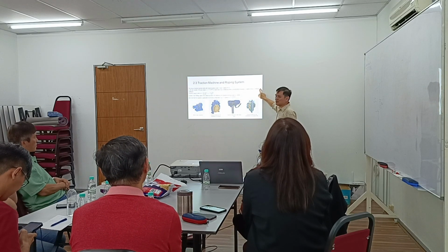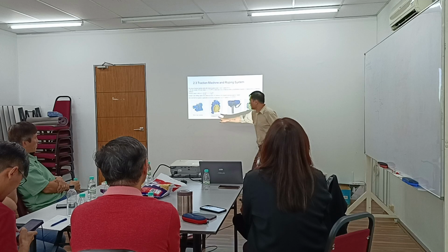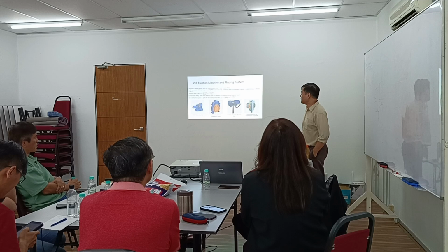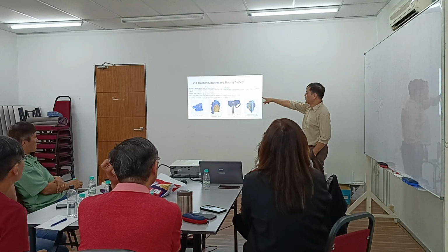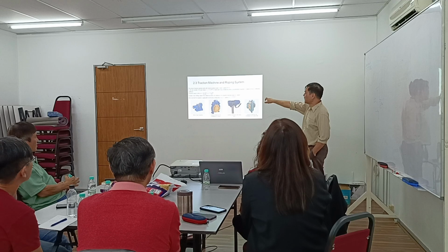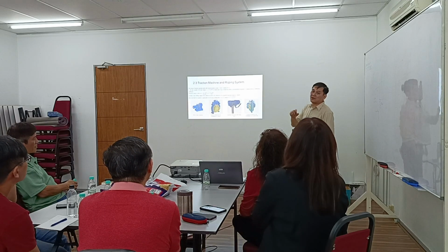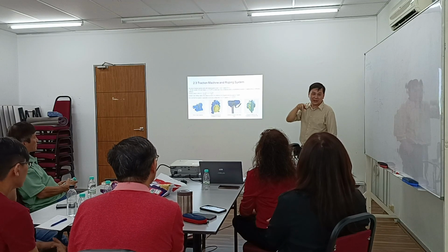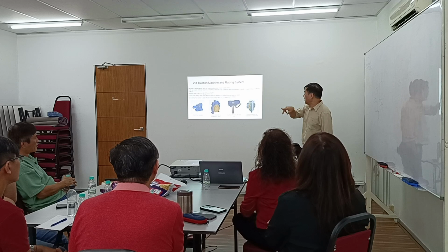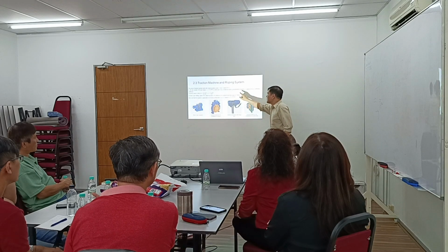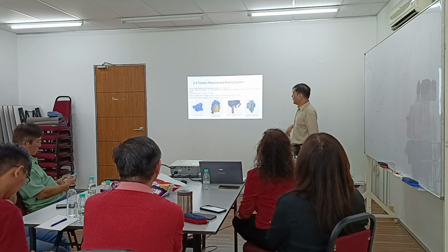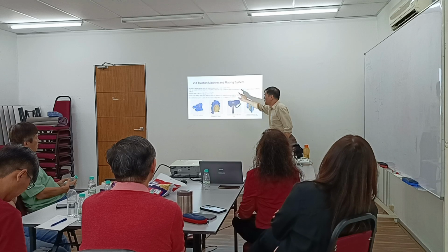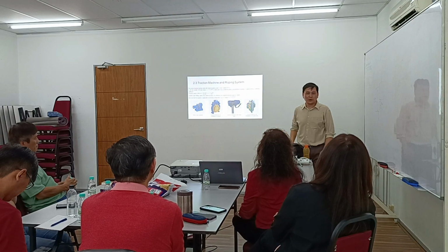So its efficiency is determined by what type of machine you are using. So for example, 1000 kilogram, speed 1 meter per second, balancing factor 45%, that means counterweight will balance 45% of the car load plus the lift car load. Then the required minimum power is 7.0 kilowatt. But can you really use a 7.08 kilowatt motor?